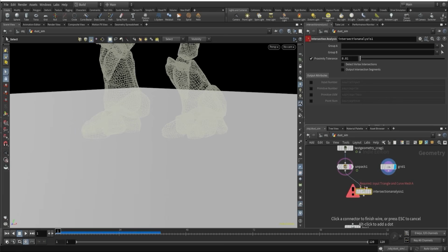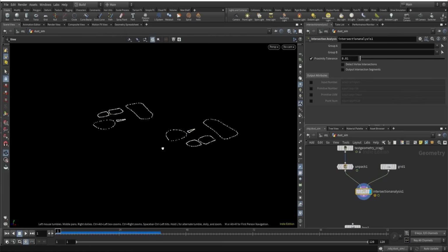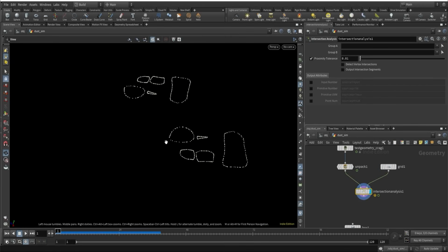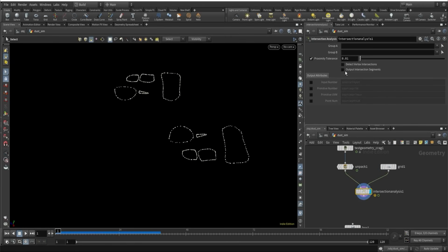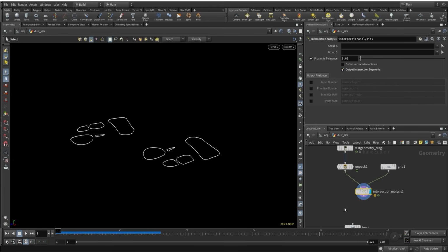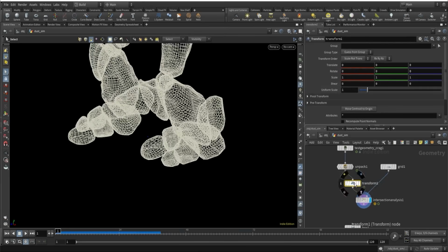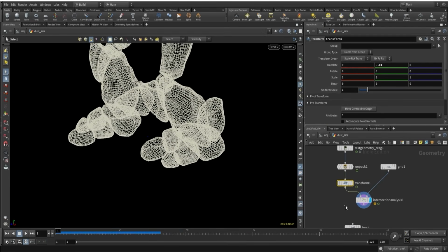So if I connect these, it will give me that intersection without changing any parameter. And I prefer turning this on, so it will give me a proper curve as well. And for the safer side, if some point doesn't intersect properly, just for the source, I can use minus 0.1. So I can just shift a bit.